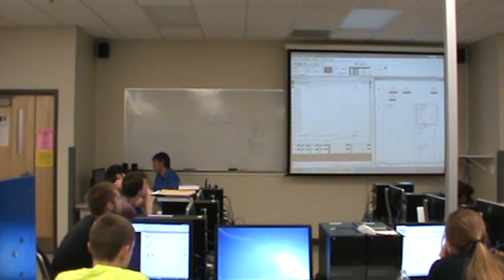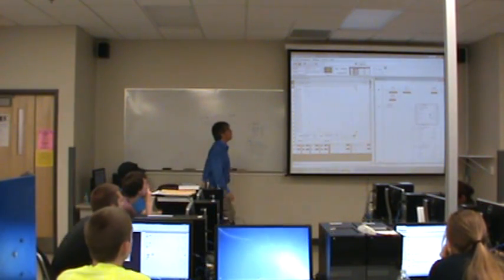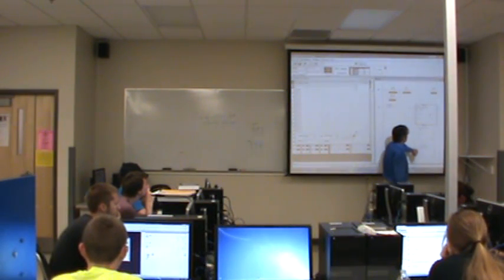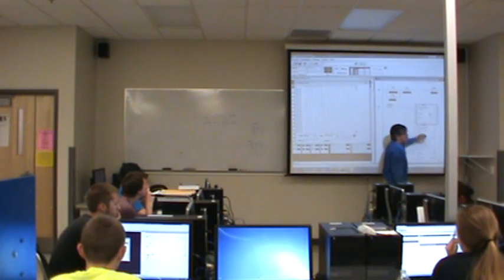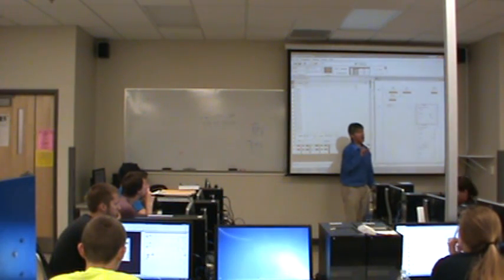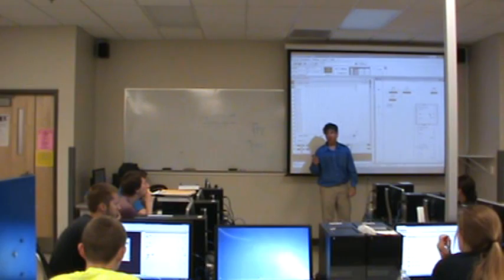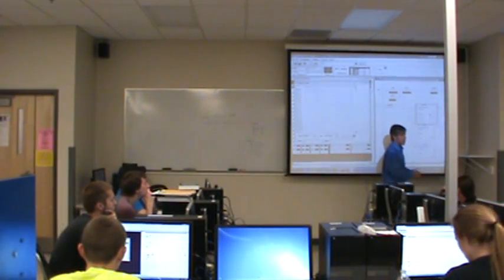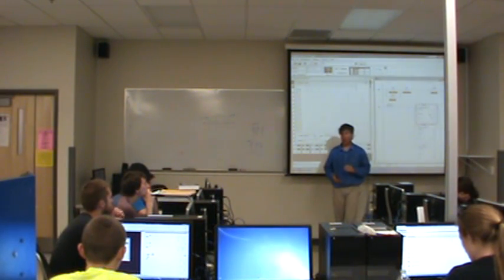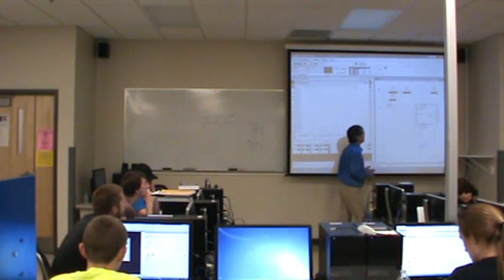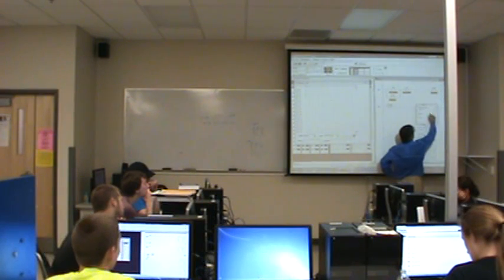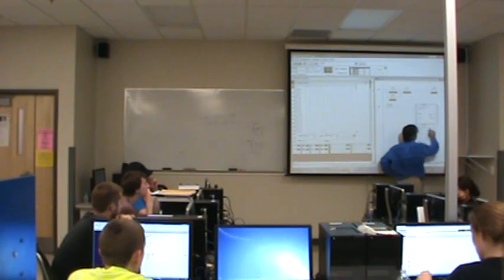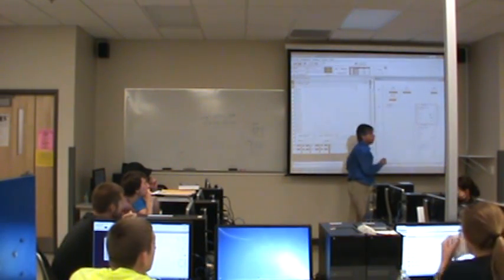This first masked move instruction, in fact the entire rung here, which has multiple outputs, which are multiple move commands, sets all of the list that's associated with the sequence output instruction. Notice the addresses are B3:11, 12, 13, all the way to B3:18. So what's going on here is we're taking a constant number, using a mask, and putting that number in the destination. Now, I didn't want to affect certain bits.